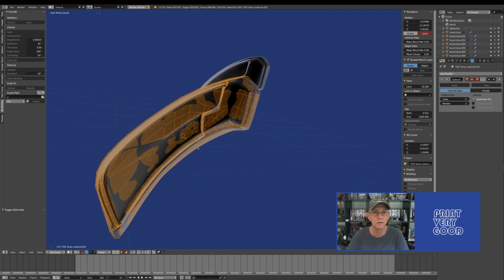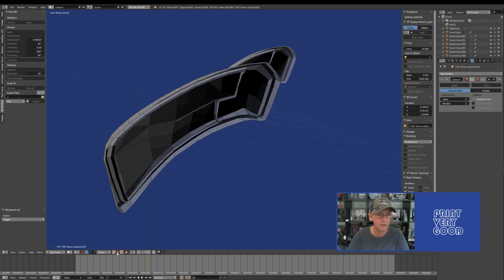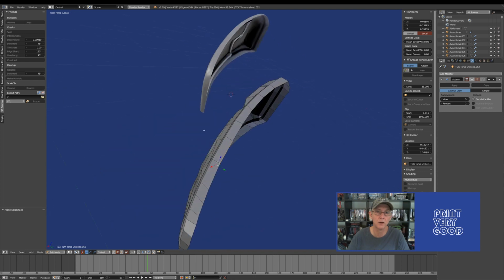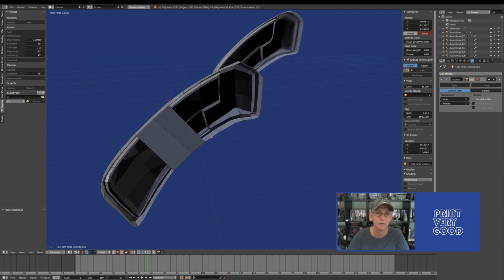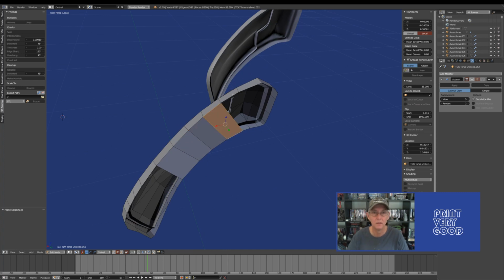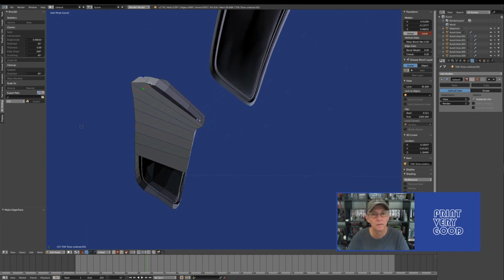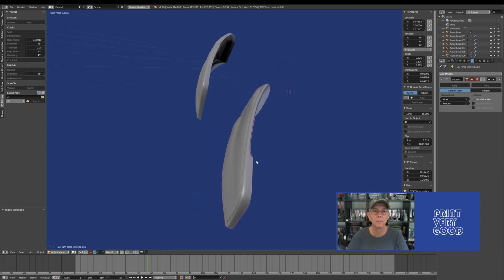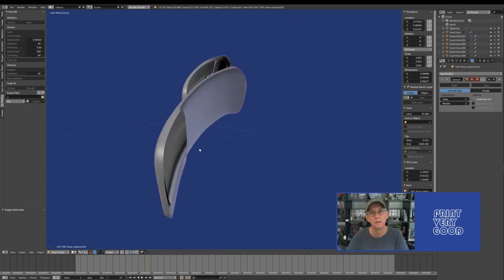So what I would do is to fill this face in if I was modeling this, and I would do that by switching to edit mode and selecting an edge, and filling it, and just working my way along. And I'm just pressing F to fill. And this is the way I would send the mesh out to print or to slice. And you can see it's just going to close the back in and give me a nice finish on a nice surface for that.